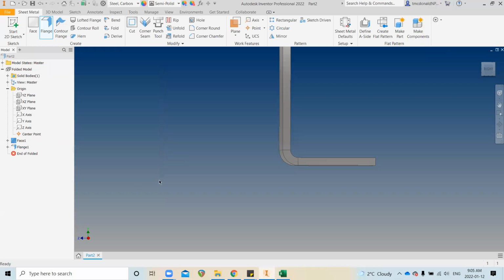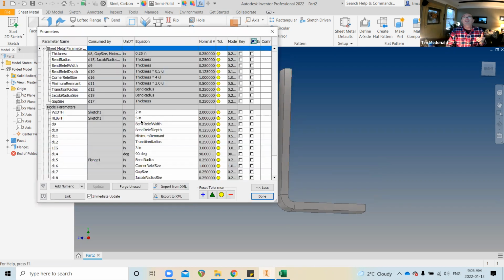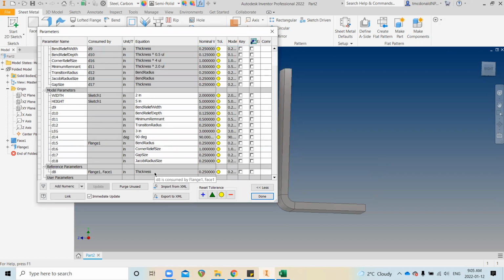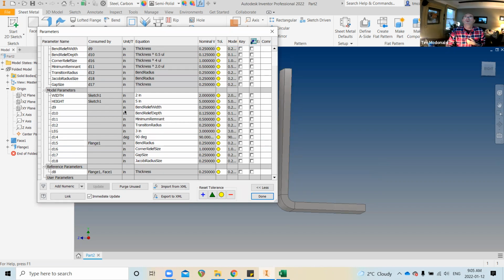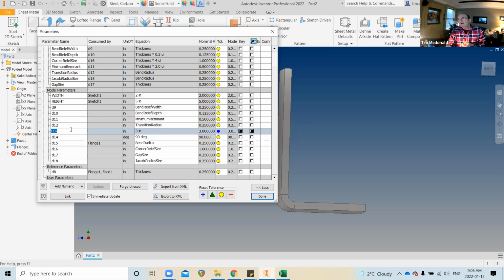And is it okay if we change the names, or we can keep other names, or if we don't put the names, is it okay? Well, if you don't put the names, you won't be able to manipulate the parameters logically. When I open up my parameters now, it will just show 3 inches of some dimension. If I am not naming it, it'll be like D1 equals 3. Well, if I put the leg value into the name, is that what you're suggesting?